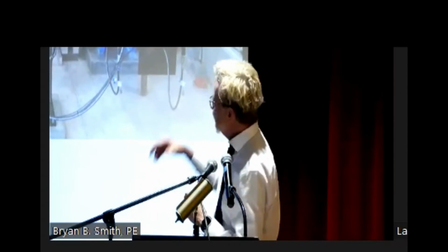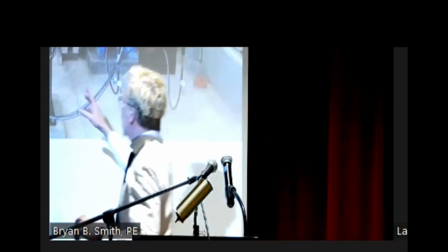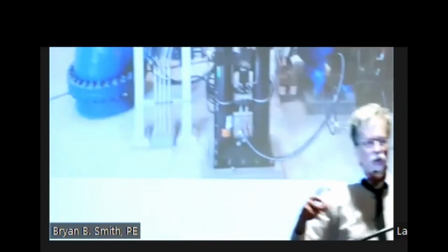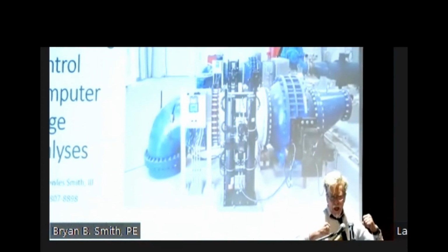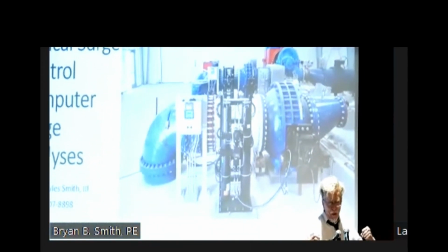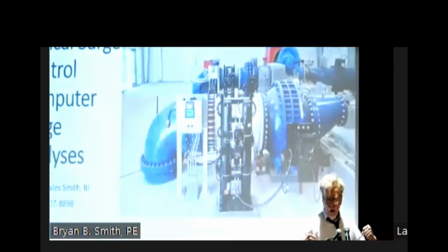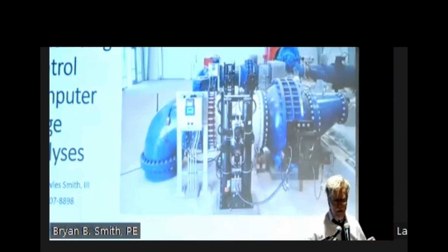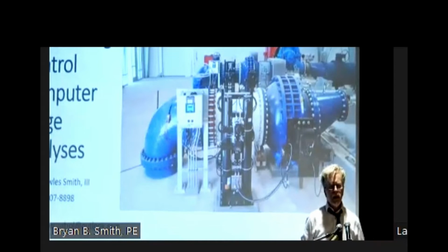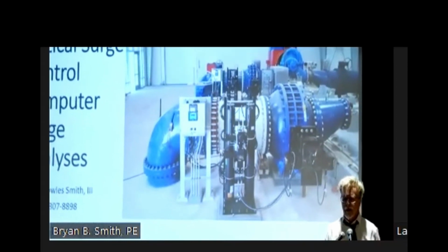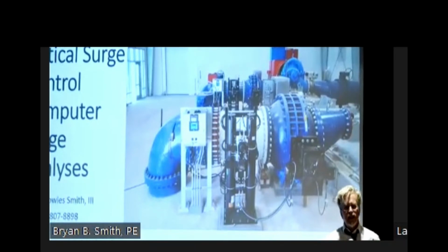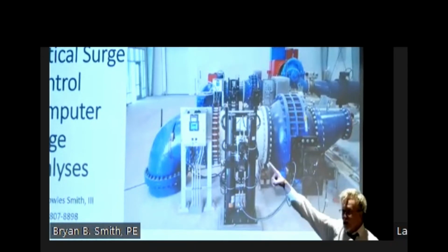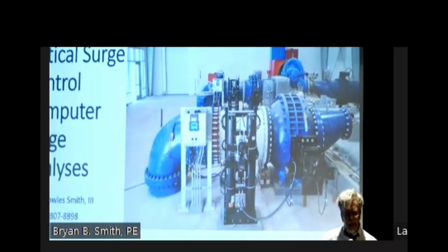So in this design, there is a hydraulic piston accumulator with stored energy. And it's like, valve, I am here to help you. If you have a power failure, you'll switch a solenoid and I'll drive the valve closed. But wait a minute, how fast do I need to close? Well, in the case of New Orleans, I need to close really fast because there's a surge vessel right there and it's going to send energy back at me.